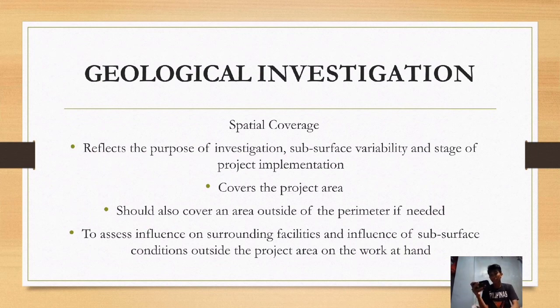And last, initial coverage should reflect the purpose of the investigation, subsurface variability, and stage of project implementation. It should cover the project area, and should also cover outside the perimeter if needed, to assess the influence on surroundings and facilities, and the influence of subsurface conditions outside the project area on the work at hand.